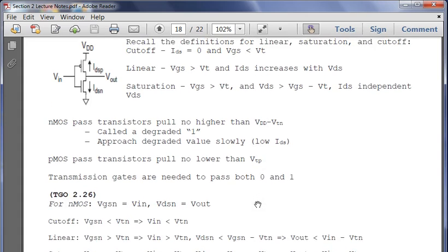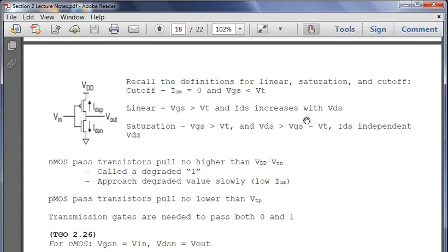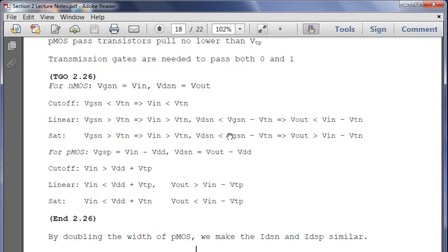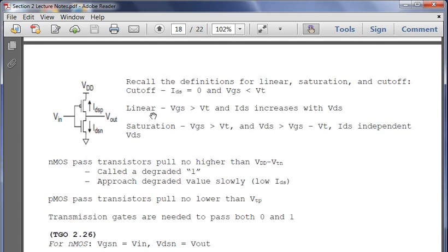And so applying these equations in order to figure out how the threshold voltage and the input voltage actually impacts the NMOS and PMOS transistor operation, we are going to talk about cutoff first. Our original gate source voltage of the NMOS, which we relate to Vin, is less than VTN. We recall we have our transistor up here, right?